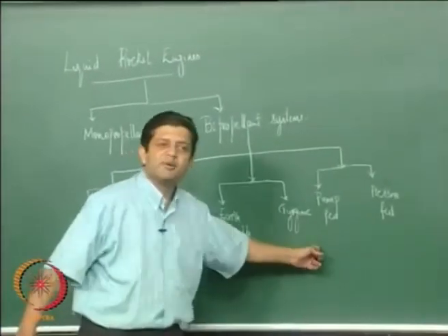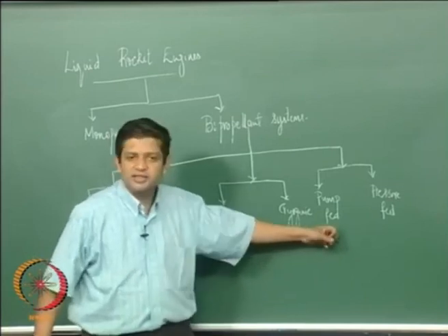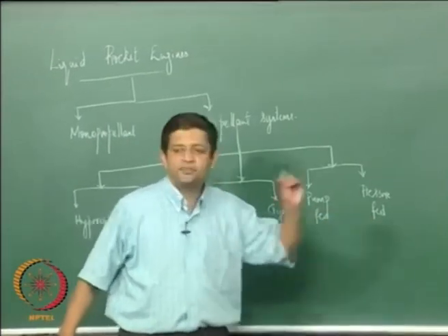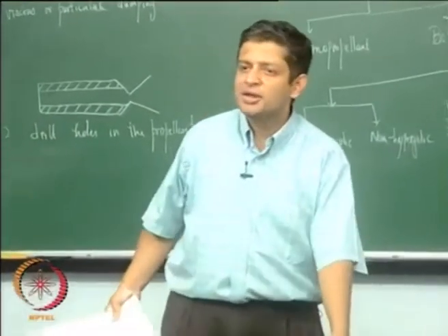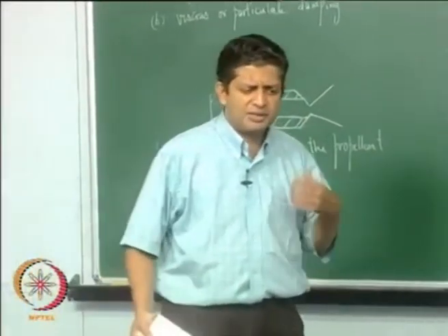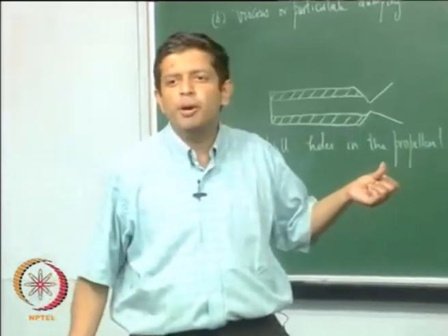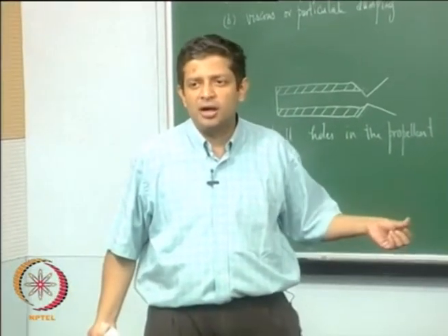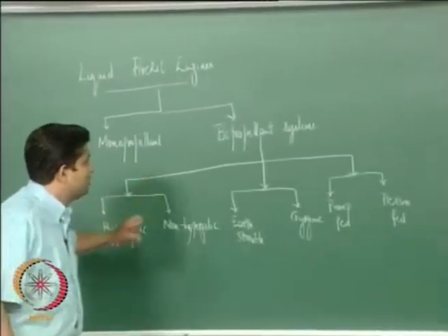If you have a turbo pump fed system, then it is called a pump fed system, and if you just pressurize the tank and let the liquid come out at high pressure, that is called a pressure fed system. Usually pressure fed systems are low thrust devices, whereas turbo pump fed systems are very high thrust devices. We will discuss them a little more in detail.